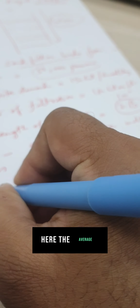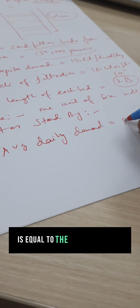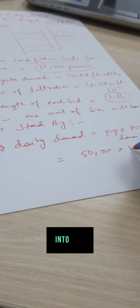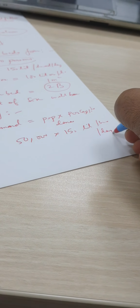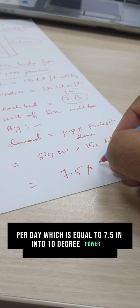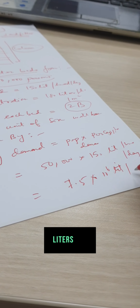Here the average daily demand is equal to the population times the per capita demand, which is 50,000 into 150 liters per head per day, which is equal to 7.5 into 10 to the power 6 liters per day.